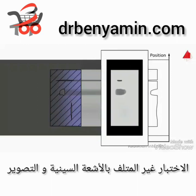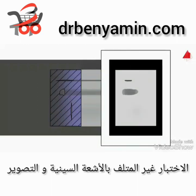And this is what the complete X-ray image of the sample looks like. The originally depicted sectional plane of the sample is shown as a dashed line. Places with defects appear darker because a more intense radiation reaches the image capture unit. As expected, the vertical crack is virtually undetectable.